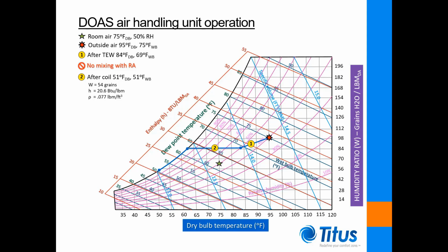Note that the dew point temperature of the air entering the coil is higher than that achieved by the mixing type air handling unit, resulting in a higher entering air enthalpy, thus requiring more energy per pound mass to condition the air to its off-coil conditions. After leaving the coil, the mixture then experiences the sensible heat gain described as it is delivered to the space.